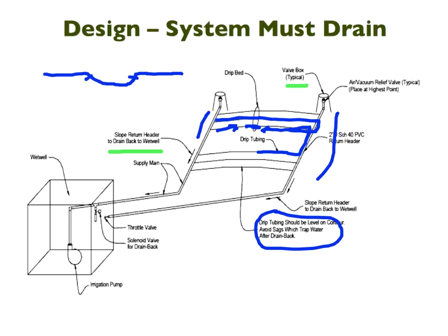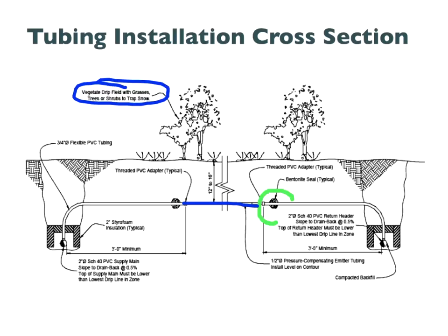I presume this is secondary treated effluent. If it's secondary treated effluent, then make sure you have a good secondary treatment. I'd guess at 0.05 you should be okay. That's pretty low. I would hesitate at 0.1, because the water isn't going to move, and that's all there is to it.